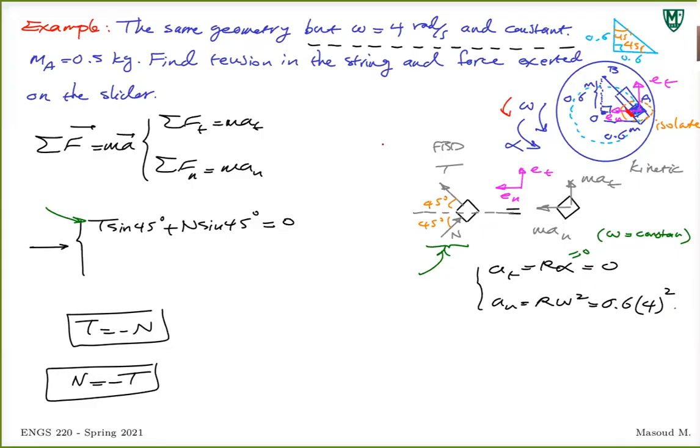When I draw the free body diagram with my assumption, I realize that it doesn't make sense. The only way that N could exist, which it does, is the opposite. So you have two options: either flip the direction of N on the free body diagram right now and write it again, or continue solving the problem. But remember, wherever you have N, you have to put minus N. Mathematically, you can still solve this. You just get a negative value for N, you plug it into the second equation, and you can find your tension, T.